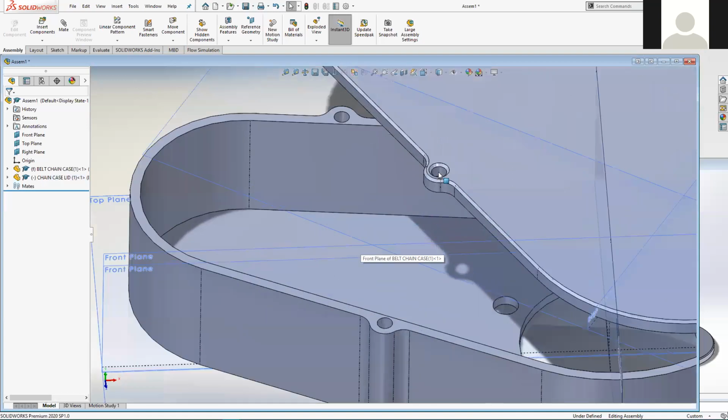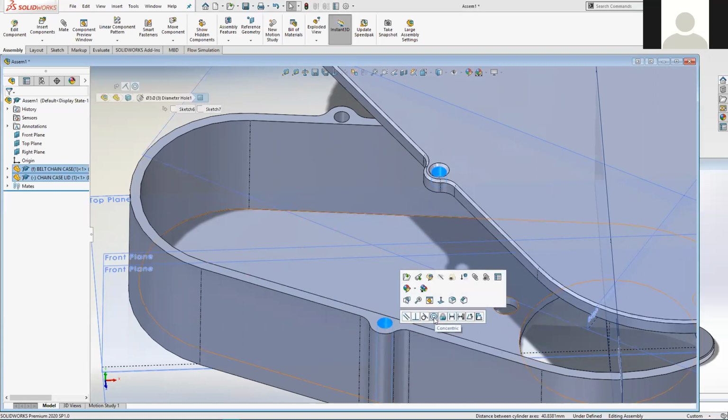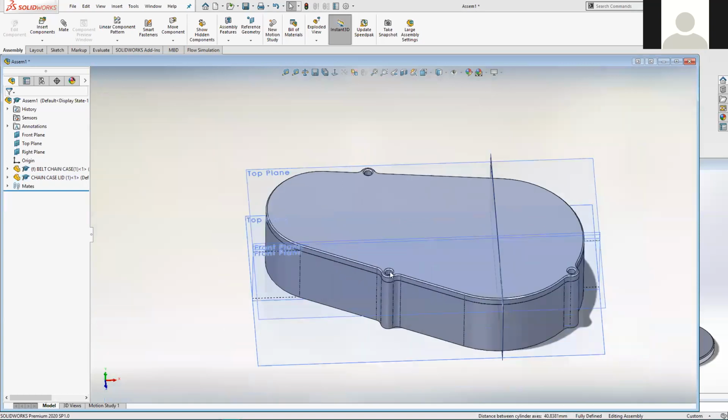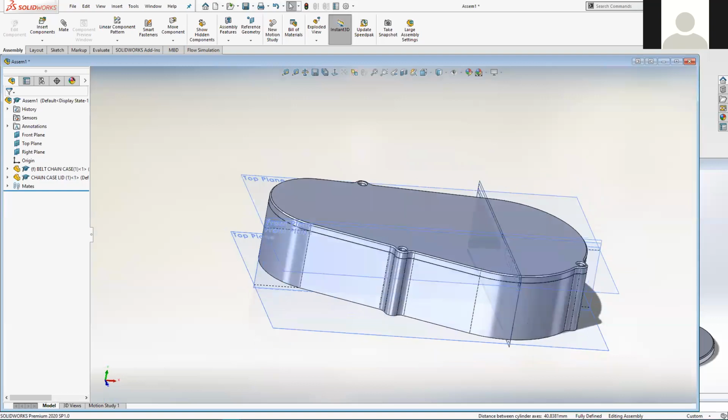So I'm going to get the internal cylindrical face of that hole, hold down Control, select the internal cylindrical face of that, and make them concentric with each other. Yes, they match perfectly. Had the distance on this lid between that hole and that hole been slightly different to the lower, it would have thrown an error, but it didn't.